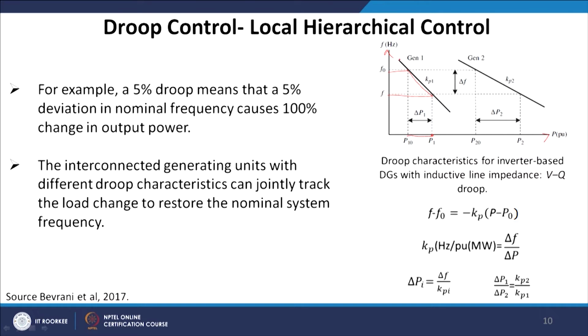Now, this characteristic may be suitable for generator 1. Similarly, we can have another droop characteristic for generator 2. For the same frequency change, the power may change, but the change in power for generator 2 is different than for generator 1.